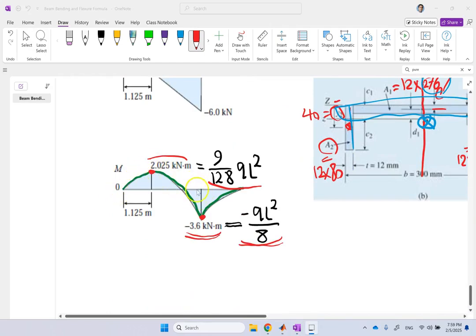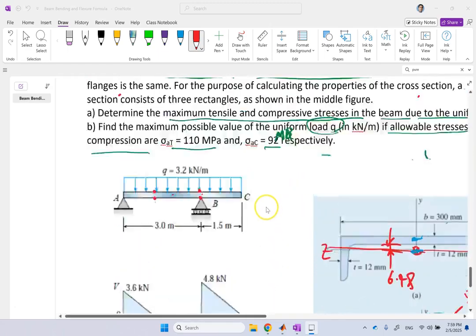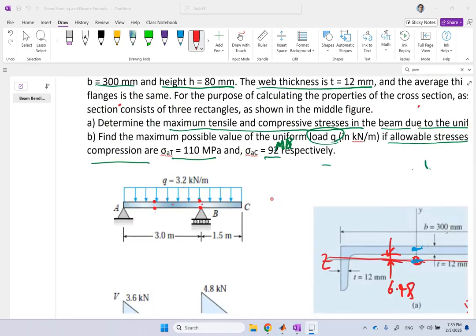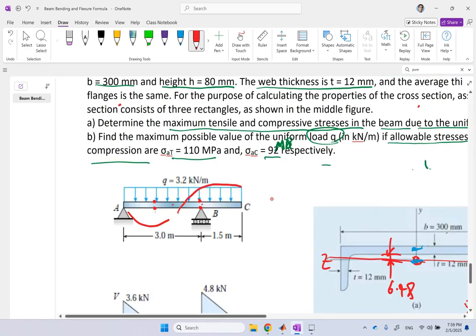You see here in the main span of the beam, the moment is positive up to a point, basically to the right side of my critical point, it's positive, and after that it goes negative. Okay, and positive bending moment means you're gonna bend like this, and negative means you're gonna bend like that. Now if you bend like this downward, you know on the top you have compression, and on the bottom you have tension. And here is the exact opposite. On the top you have tension, on the bottom you have compression.